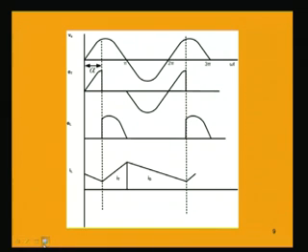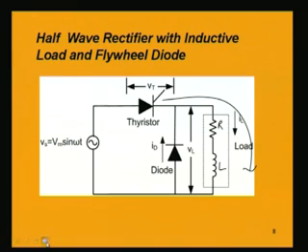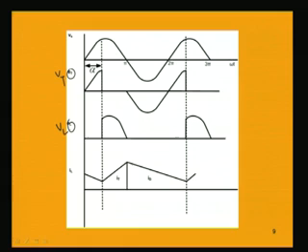So, this is the input voltage waveform Vs, it is Vt, this is VL, these notations are to be corrected. So, when we have non-conduction of the thyristor, input voltage and thyristor voltage are same, because it is not conducting.